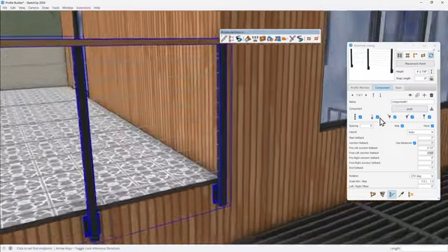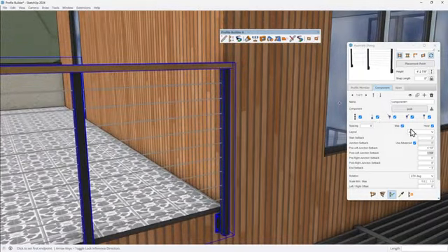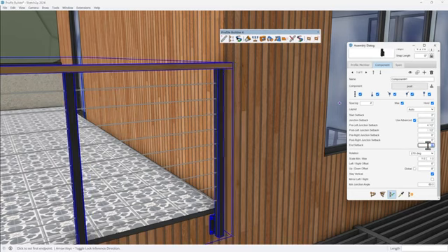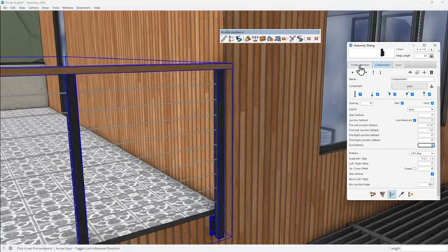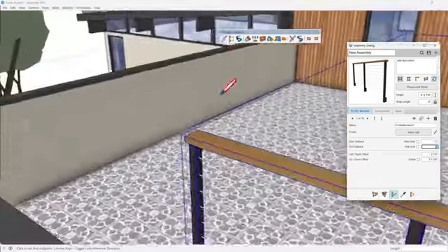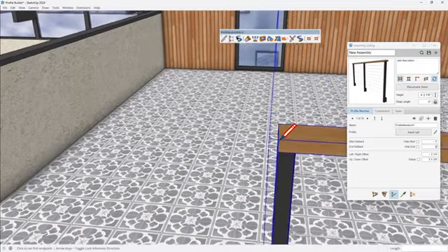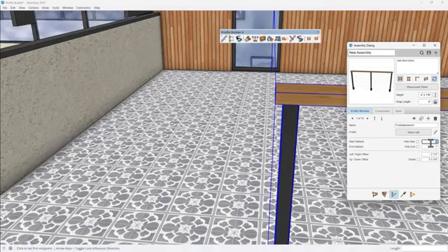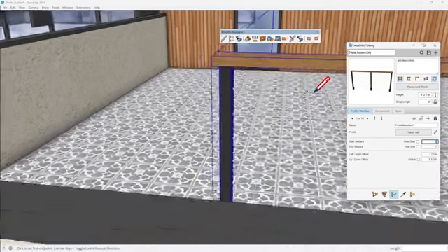Now, other things that I can modify while I'm in this live edit are the end setbacks, right? So I could set now the component end setback is 3 inches. Maybe I set that to 5. And then the handrail. So I go to profile member and I'm on the handrail. Maybe the end setback to there is 1, which also then over here, remember when I built this, I didn't have any overhang on this. So that start setback, it defaulted to 3 inches based off of the post. When I set that to 2, that way I get a little bit of that overhang.